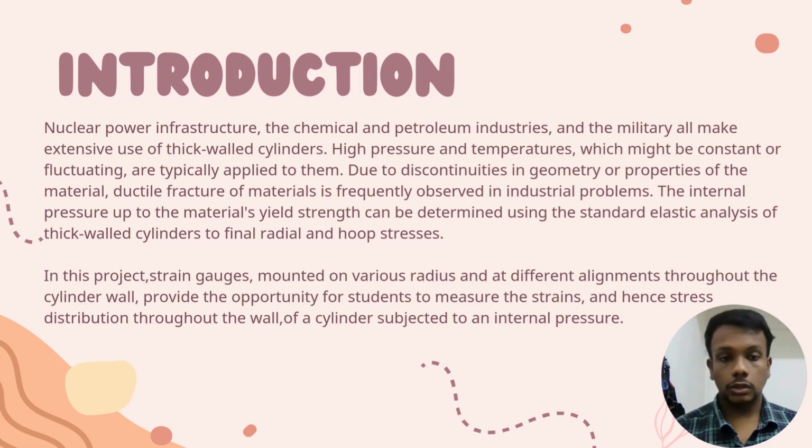Today I want to talk about the introduction of the thick cylinder. Nuclear power infrastructure, the chemical and petroleum industries, and the military all make extensive use of thick wall cylinders. High pressure and temperature, which might be constant or fluctuating, are typically applied to them. Due to discontinuities in geometry or material properties, ductile fracture of the material is frequently observed in industrial problems.